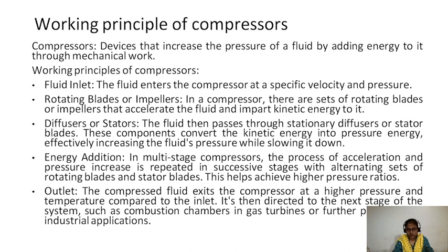Then the fluid is passed through stationary diffusers or stator blades. These components convert the kinetic energy into pressure energy, thereby increasing the fluid's pressure while slowing it down. They won't increase the kinetic energy, they will rather increase the pressure energy. They will add energy to the fluid in terms of pressure energy. Now, energy addition may happen in multiple stages or a single stage. This process of acceleration and pressure increase is repeated in successive stages with alternating sets of rotating blades and stator blades. This helps in achieving higher pressure ratios.